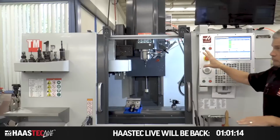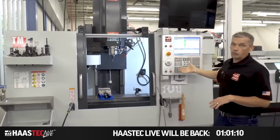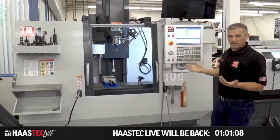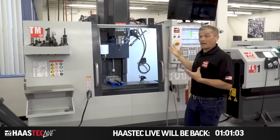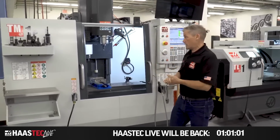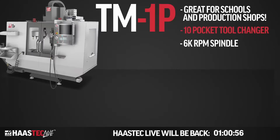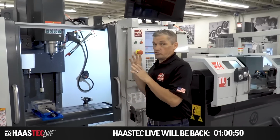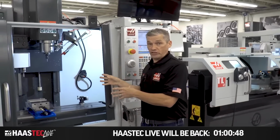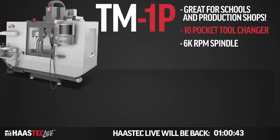In this case, this is the TM1P, the slightly improved version of the TM1. TM1 comes at about $31,000. This is $35,000, and for that extra $4,000 you get a lot of bang for the buck. You've got a 10 pocket tool changer, a faster 6,000 RPM spindle. It really takes it from a more manually oriented kind of experience to really a full production CNC machine. This is just a step away from our VF2 style of VMCs.